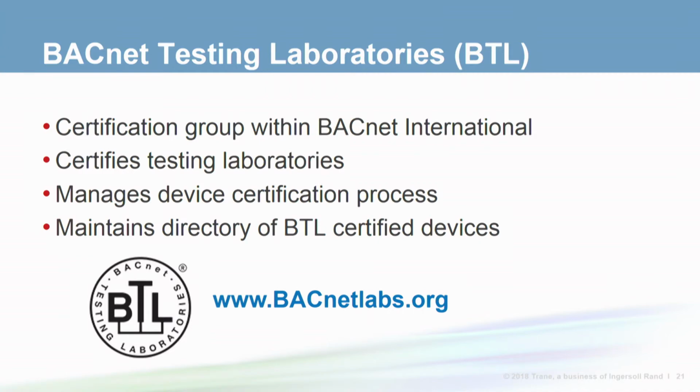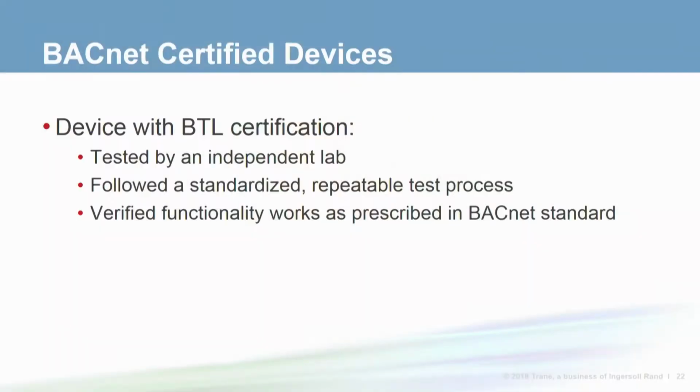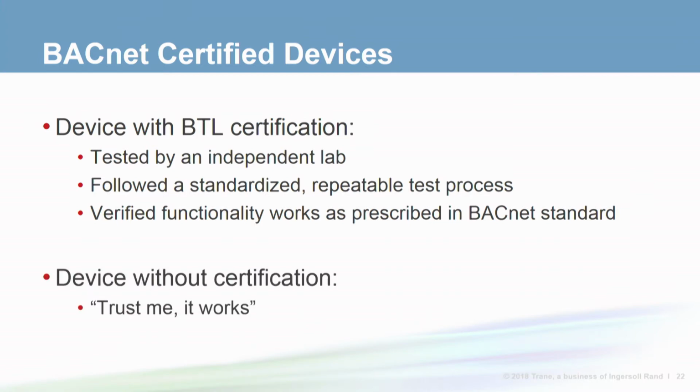Certification is awarded after a formal test process verifies that the functionality that a device supports is implemented in accordance with the BACnet standard. So what does certification mean to you? When you have a device with BTL certification, you know that an independent lab has tested this device using a standardized and repeatable process to verify that the supported BACnet functionality works as expected. Without certification, you have a "trust me it works" device. As a general statement, there is more risk using a device that is not BTL certified.